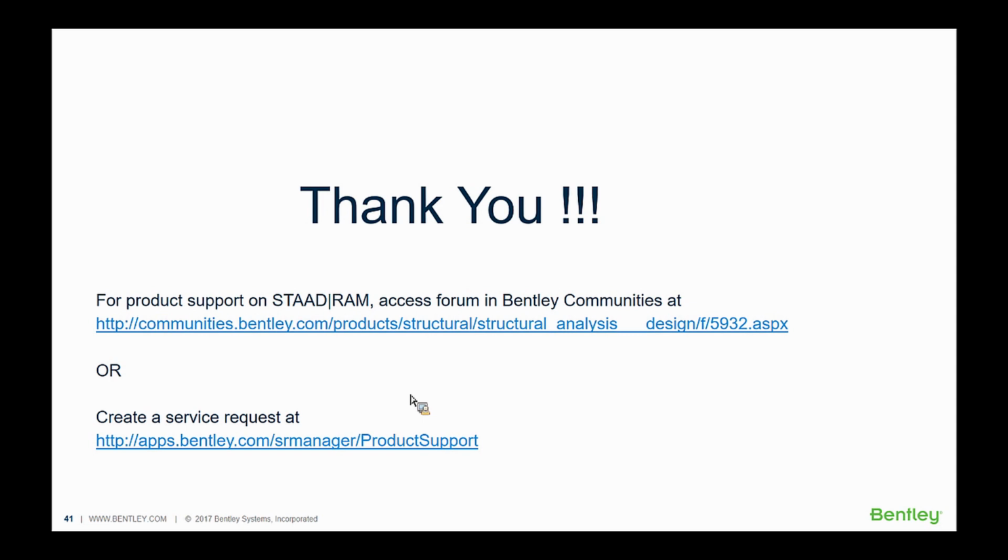The software can definitely solve for the number of modes that you ask it to solve for. So you should take a look at the cumulative mass participation, and ensure yourself that 90% or more is being considered.